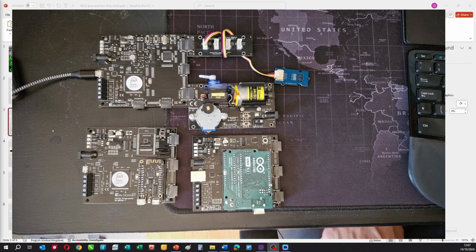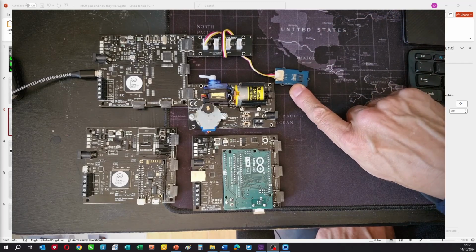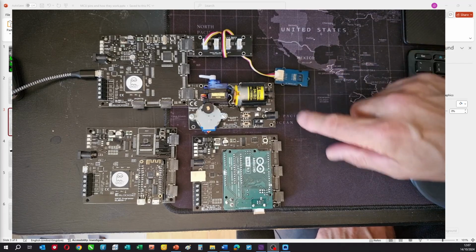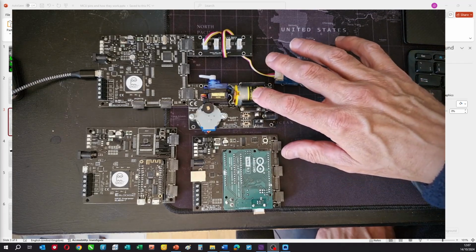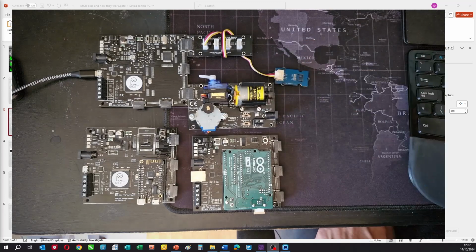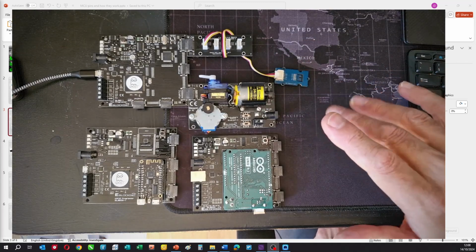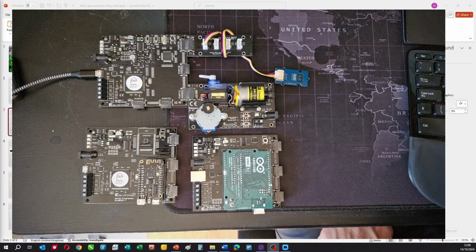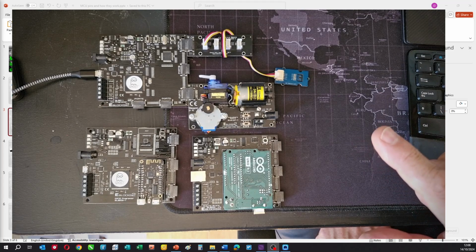Now before you connect things, like for example a sensor or a motor that requires pulse width modulation, you need to be making sure that the pins you're connecting to have the capabilities. So let's see how that works in a more diagrammatic format.